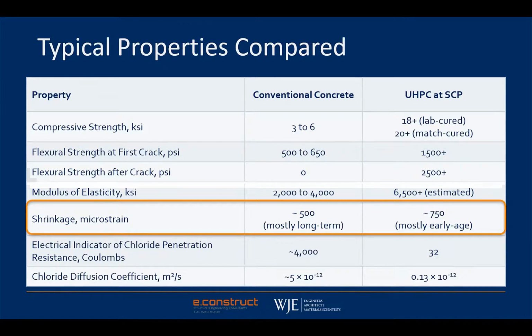Next topic I want to talk about is shrinkage. Taking a step back, a primary contributor to cracking in concrete structures is restrained shrinkage. That is the tendency for concrete to get smaller as the mixed water evaporates or there's chemical consumption of that mixed water due to hydration.